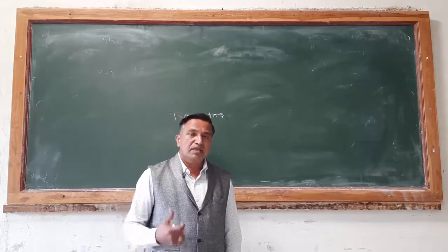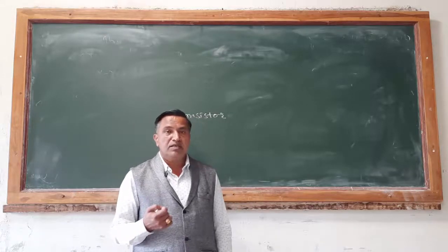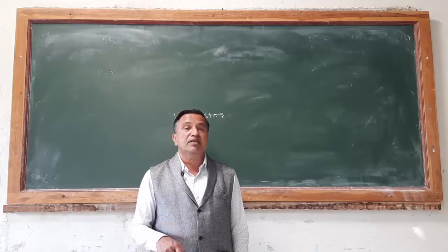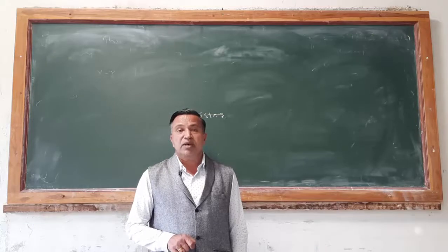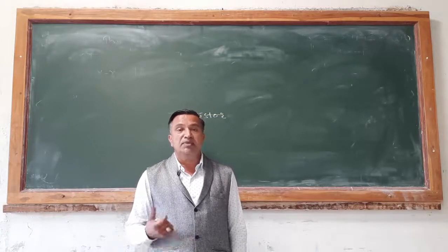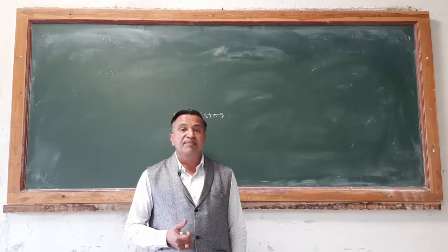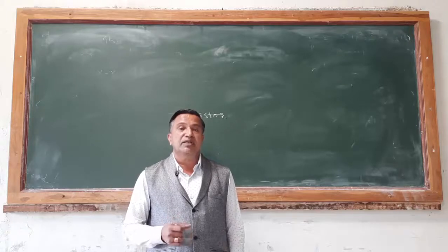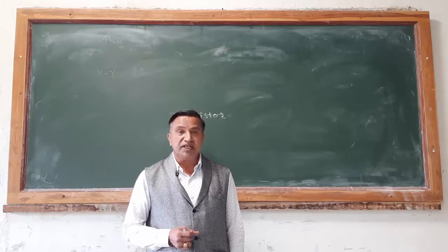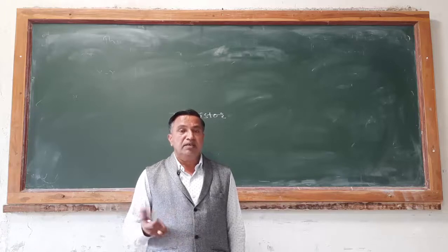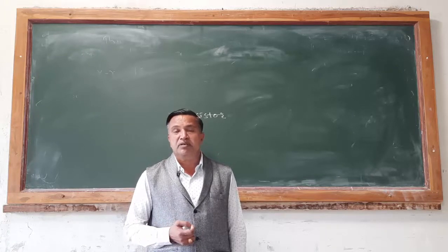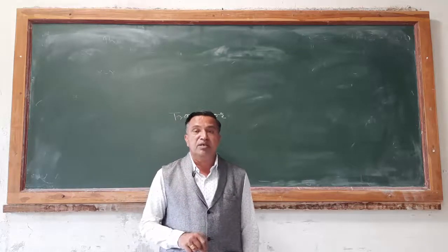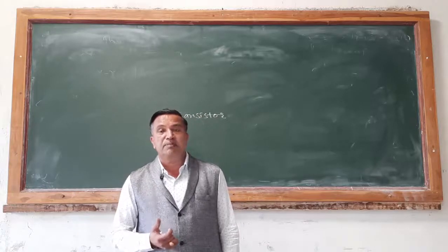At the same time, in the forward bias junction, the current flow through the semiconductor diode becomes maximum, while the resistance in the forward biased diode becomes minimum. While if the diode is connected in reverse bias mode, the current generated in the junction is very small, in the microampere range. At the same time, the resistance across the semiconductor is very high.